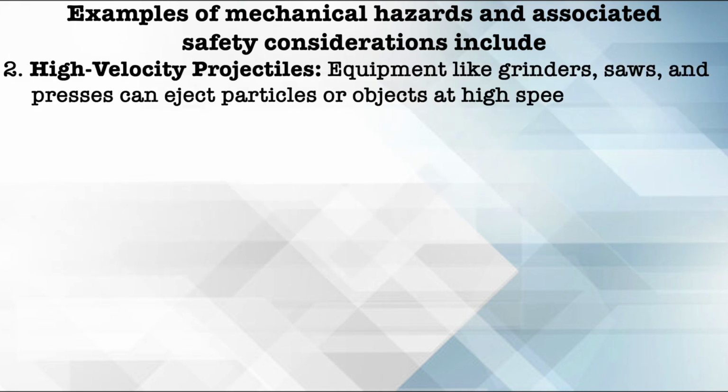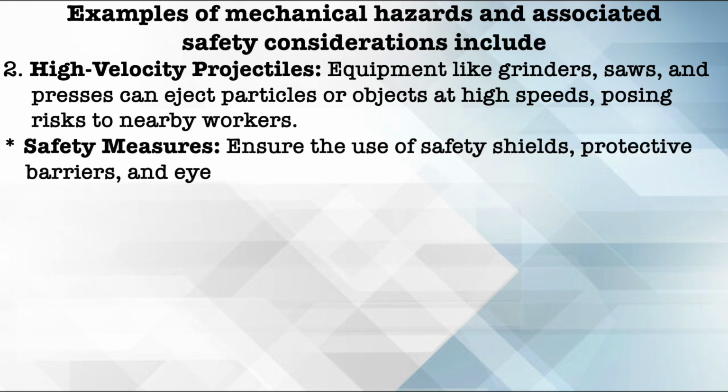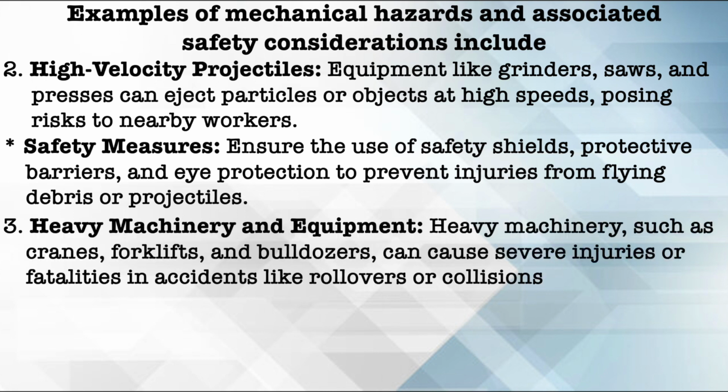High velocity projectiles. Equipment like grinders, saws and presses can eject particles or objects at high speeds, posing risk to nearby workers. What are the safety measures? Ensure the use of safety shields, protective barriers and eye protection to prevent injuries from flying debris or projectiles.